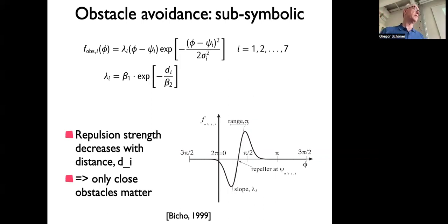That's the maximum distance. So it always drives up to anything up to that distance before it even takes the obstacle points into account. So that's clearly a local approach, right? And that's actually the spirit in which these reactive approaches are used today. For instance, I mentioned many of them actually use the potential field approach, which is not really better, but maybe just because it's more known. And typically that's about one vehicle size that you're using. It's actually even true for these very primitive robots.